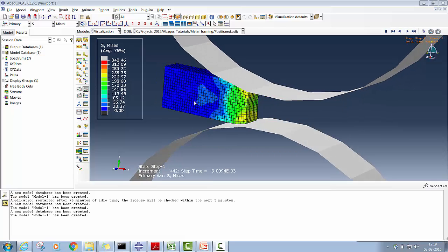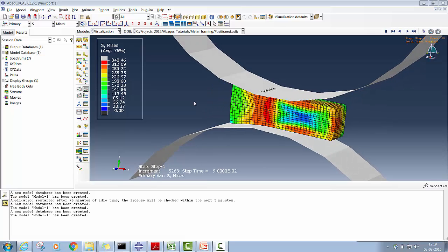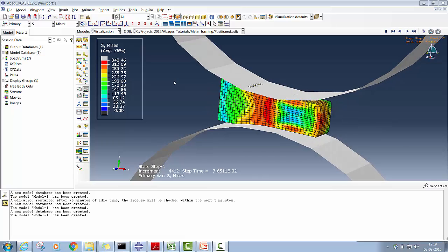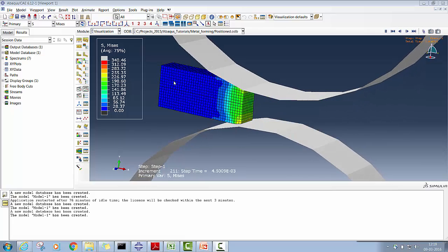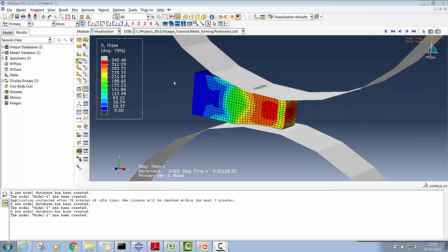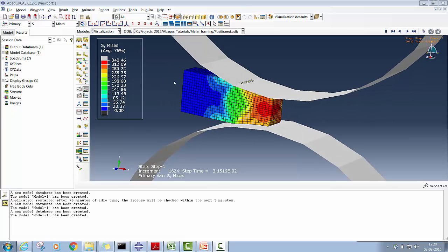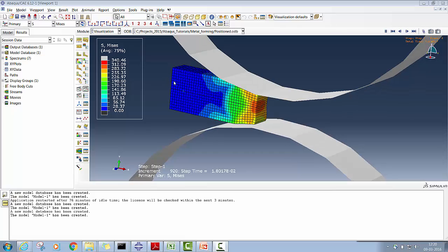Through this kind of process simulation, we can generate a lot of insight in terms of the metal flow and the geometry deformation contour, that is the equivalent, or I will say plastic strain contour, and the displacement part, of course. So all these things we can generate through this kind of process simulation. Here we are taking the example of rolling process.